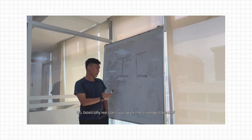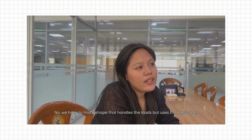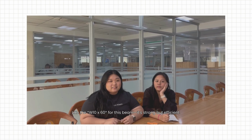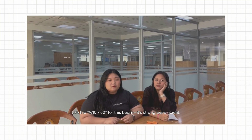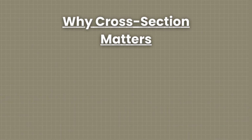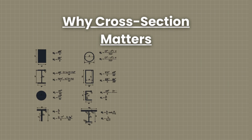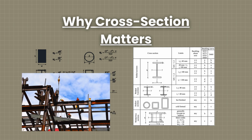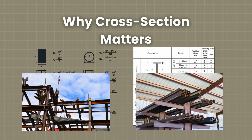So basically, we can't pick the strongest beam. No, we have to find a shape that handles the load but uses the least steel. Like the W10x60, for this beam, it's too strong but efficient. Choosing the right cross-section helps the beam resist bending, which is critical to ensuring the overall stability of a structure. For example, wide flanges help distribute the load more evenly across the beam.